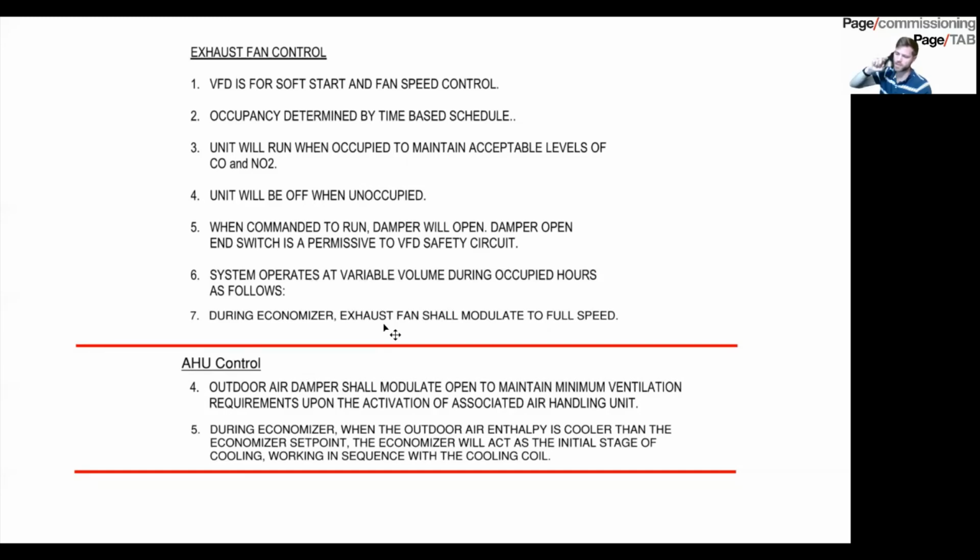And then all controls has to do at that point is say, if I'm at this speed, I'm going to be at this CFM, and I need to make sure that that CFM is about 10% less than my outdoor air CFM as a rough starting point, right? Because all buildings are going to be different. And once they program that, that should solve this issue,